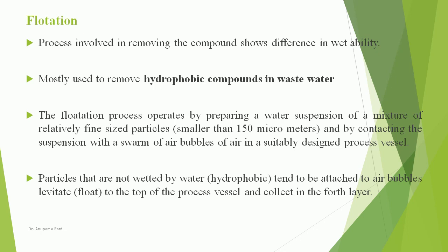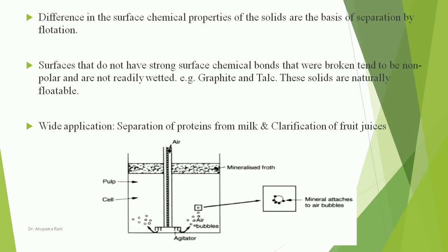Particles that are not wetted by water, hydrophobic, tend to be attached to air bubbles, levitate, float to the top of the process vessel and collect in the froth layer. Difference in the surface chemical properties of the solids are the basis of separation by flotation.